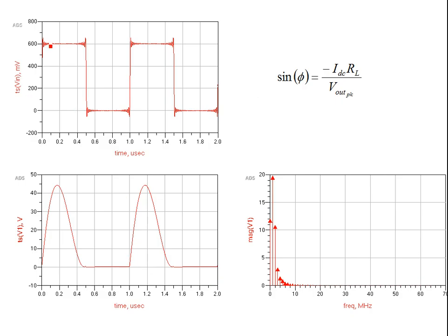You see over here we have 50% duty cycle. This is about 0.5 microseconds over here, the time period when you have the square wave. And this is when you don't have any stimulus, the switch is open. So here the switch is closed, switch is open, and this period is about 0.5 microseconds, so 50% duty cycle. You can see it from here.